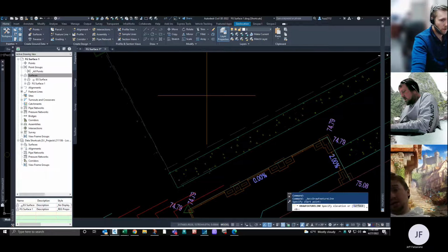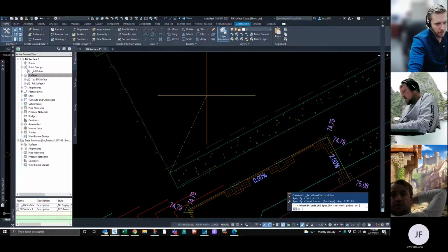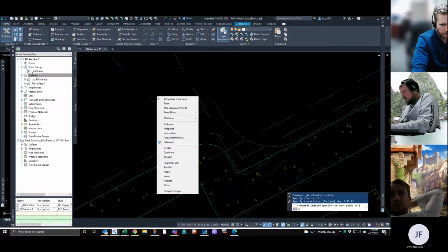Is that where you are? I have the flow line elevation, so we just need to go 6 inches above that, right? Yep. So the flow line is 73.33, so that'll be 73.83. And then we're just going down to this corner.